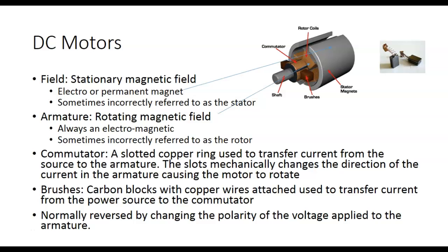Probably the one that runs the radiator fan too, because most of our cars now have motors on the radiator, since most of our cars now are front wheel drive, right? And your radiator's off to the side. In older cars, which were rear wheel drive, the radiator was mounted forward, and the fan actually ran right off your motor. You didn't run it electrically. But what's nice about controlling it electrically is that you can turn it off or turn it on and make your car run more reliably.